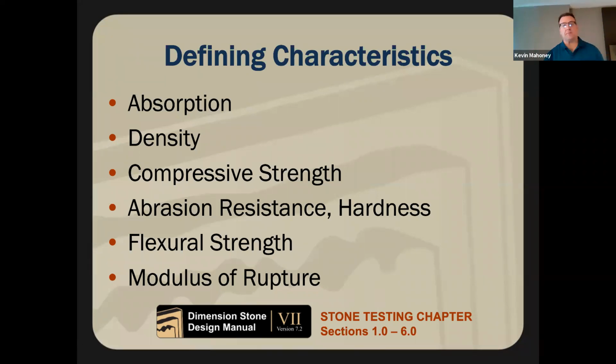And the modulus of rupture, most commonly used with marbles, some of the water sensitive marbles in exterior applications can change and rupture or bend or curl. Other stones can blow apart too. In an ASTM test for freeze thaw, they actually soak a stone in water and freeze thaw it until it blows apart, and we're able to give it a rating on whether it's ASTM tested for freeze thaw sustainability.